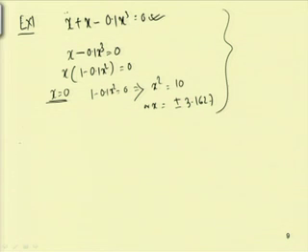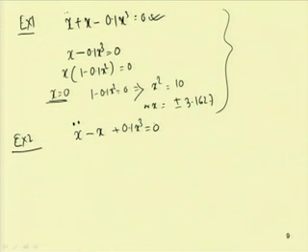So, let us take another example. In this case let us take the equation in this form: x double dot minus x plus 0.1 x cube equal to 0. The previous case is similar to a Duffing equation with a softening type of spring with cubic nonlinearity, that is, we have the minus 0.1 x cube. In this case we have taken an equation where the linear stiffness part is written as negative.